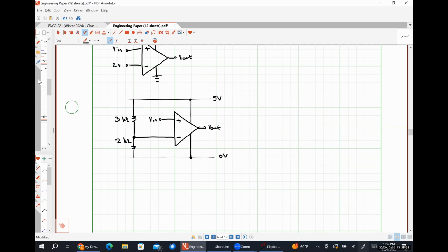All right, so this is for an inverting comparator. Whenever your input is less than your reference, your output goes up. So the graphs that I'm looking for on homework: how did you get that? You just clicked on VN? Yeah. To put that curve there, click on VN and it puts my input curve on there.